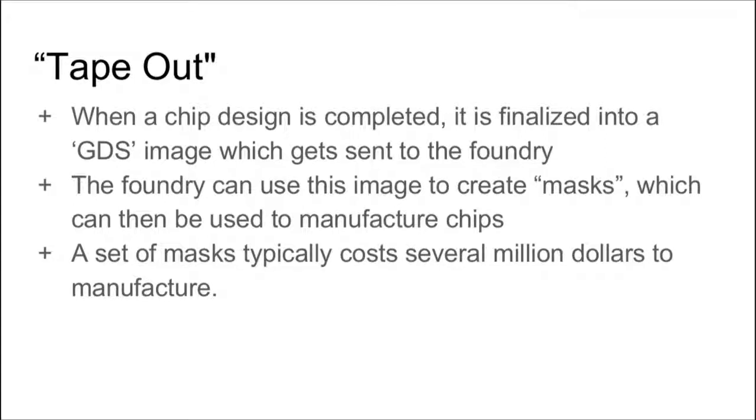manufacturing steps. They make these things called masks, which are essentially, for a single chip, you might have between 80 and 150 really high purity pieces of glass with chrome on them that etch out these really fine-grained features. These masks genuinely cost millions of dollars. The precision is extremely high on the chrome etchings, and the glass is very pure. But basically, after you tape out, the chip is complete and the actual manufacturing is started.